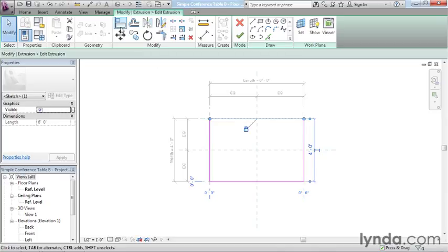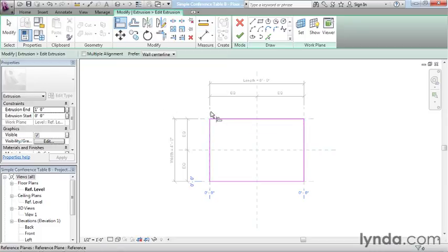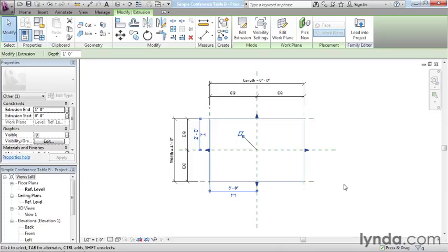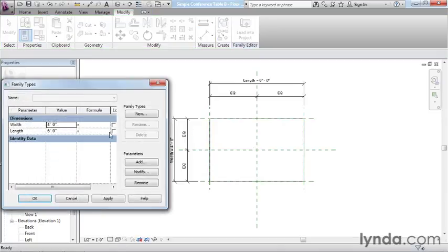Or the easier way to do this is with the Align tool. So I'm going to click on Align, click on the reference plane, and then the sketch edge, and lock it. Click on the reference plane, sketch edge, and lock it. Notice the dimensions are disappearing when I do that. Click on the reference plane, sketch edge, and lock it. So all 4 automatic sketch dimensions disappear. I go to Finish, and ultimately I really won't see anything different with respect to how it flexes.